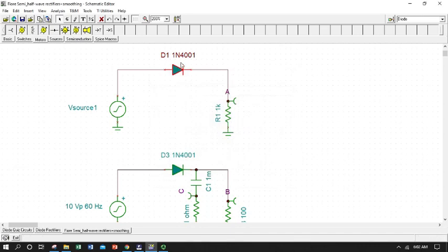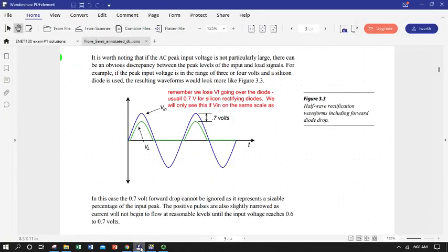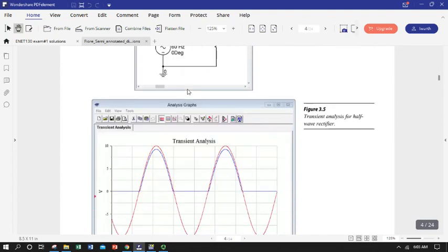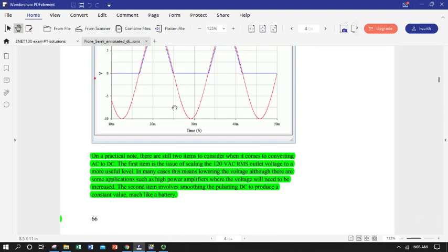If somebody is applying a voltage that exceeds the reverse breakdown of a rectifying diode, you might start to see that negative half wave that should be stopped. You may see it coming through in your output circuit, and that would indicate that somebody exceeded the capabilities of a diode. So that's a good troubleshooting tip for the future that we can look at with Tina. Okay, so we've probably covered just about everything important with simple half-wave pulsed DC rectifiers.